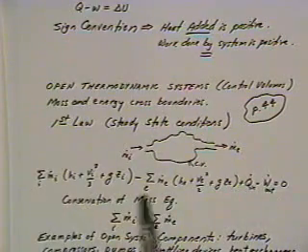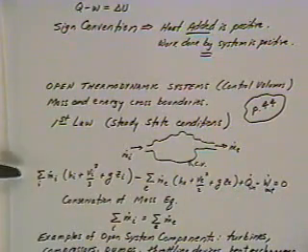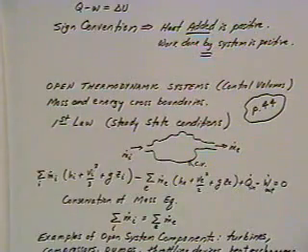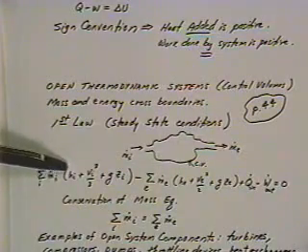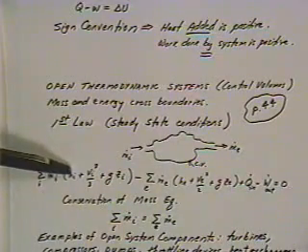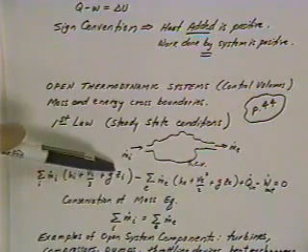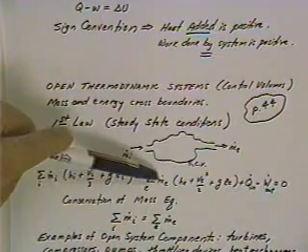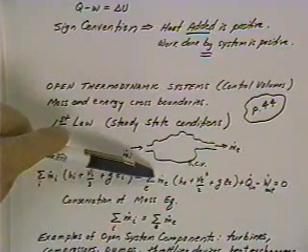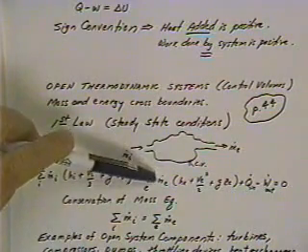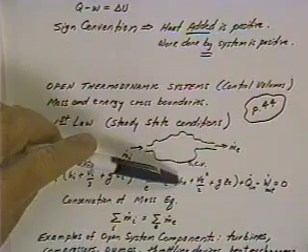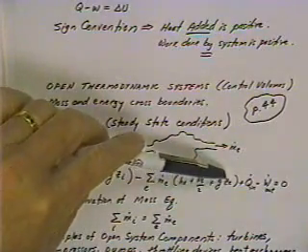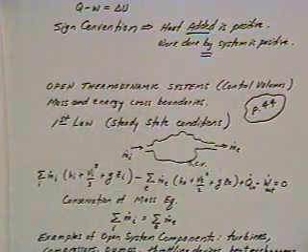This is the general formulation of the first law, where we may have multiple inlets, 2 or 3 or 4, and we sum up all the mass coming into each inlet and multiply that by the enthalpy, kinetic energy, and potential energy terms, and we subtract everything that's leaving our system. That's minus the mass exiting, however many exits we have, times the exit enthalpy, kinetic energy, and potential energy.